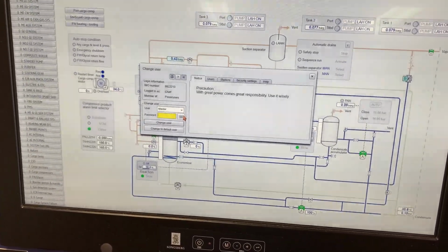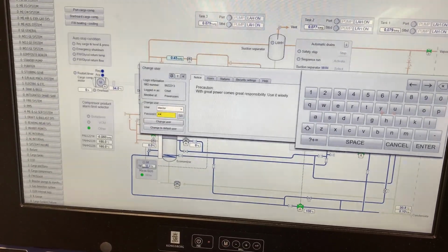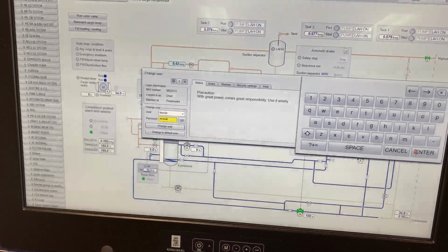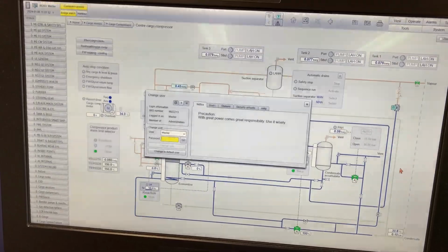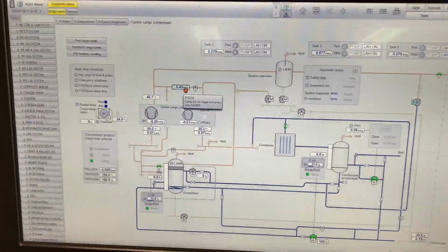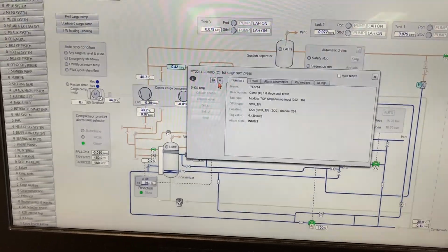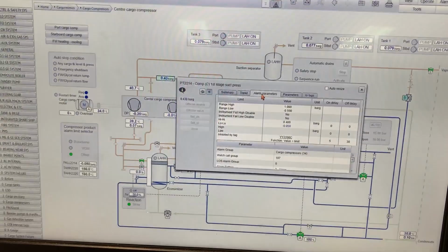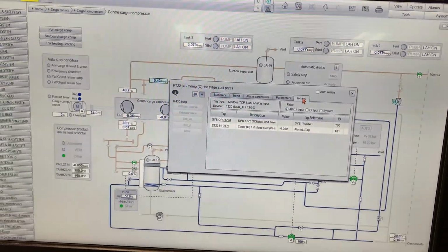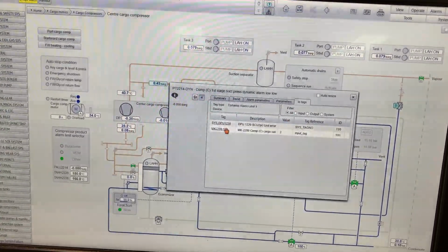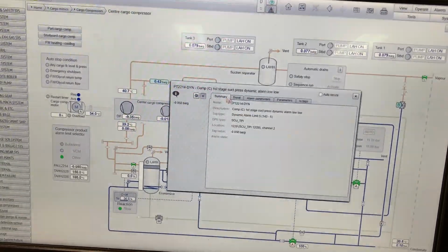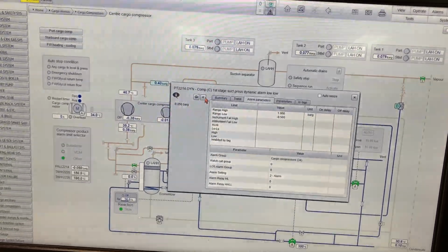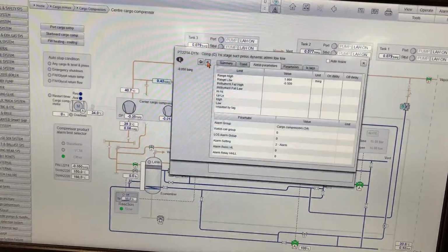I went to the CCR to set our pressure transmitter to off scan, so that it doesn't give an alarm while I am working. But the Kongsberg system doesn't let me set this signal to off scan, even when I log in as super user. Okay, we call the watch officer and tell him that we are going to the compressor room and there might be an alarm.